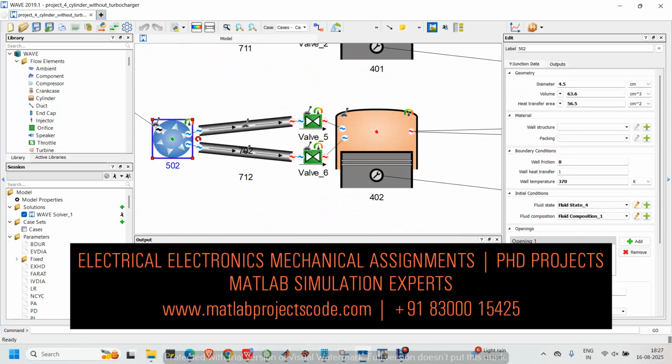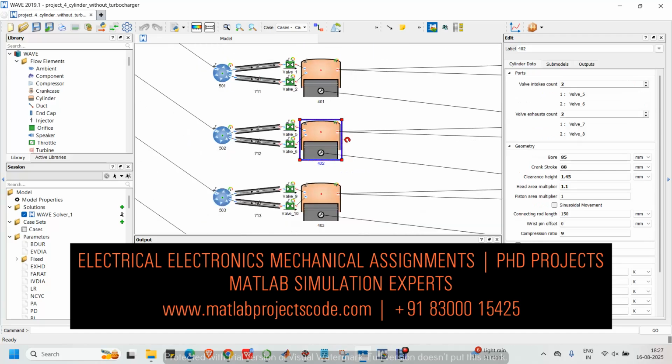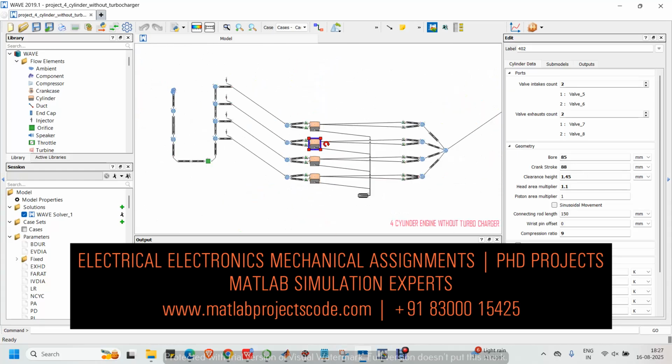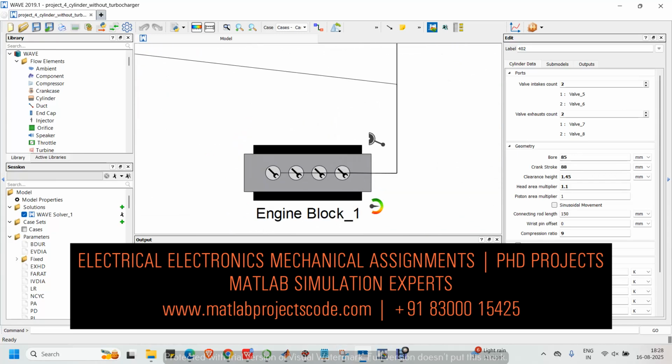You can also see that. So this is your engine cylinder, and all the data can be edited. Right now I used a bore of 85 and a crank stroke of 88. So this is my specification of a normal four-stroke engine. This is without a turbocharger. I am not using a turbocharger, and this is your engine block.